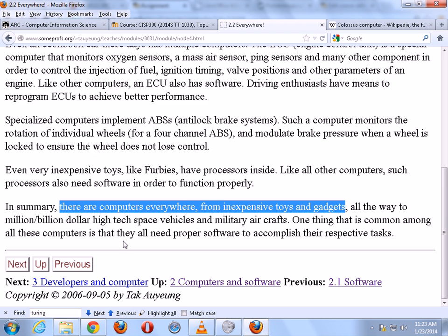You can specify the tire. It will automatically look up and program the torque wrench for the right amount of torque for, let's say, the wheel lugs. So you don't have to look up anything. There's no chance you can make a mistake unless you specify the wrong car, right?